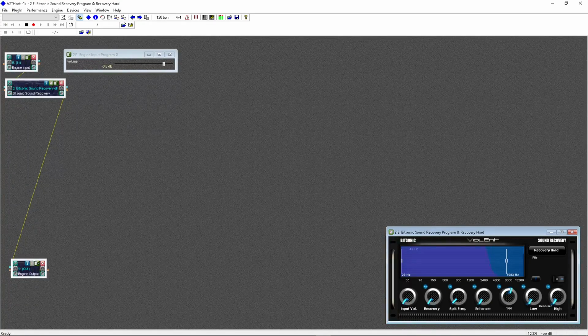It will shut down the high end. The higher you go, you'll see that purple line go to the left. Now this is your frequency spectrum right here. So I'm about 4.2 to 19.2, close to 20K. Obviously, we don't go out to 20K. So I'm going to set this probably for now right around in here, 4,800 maybe, something like that.